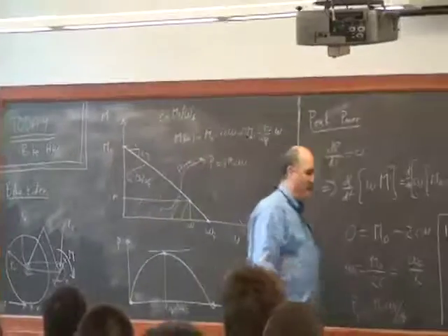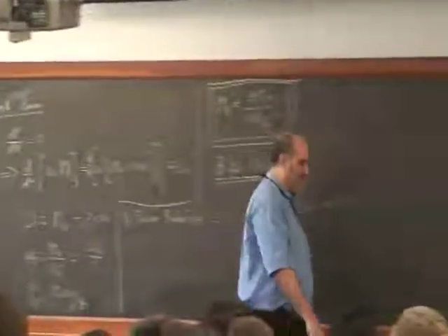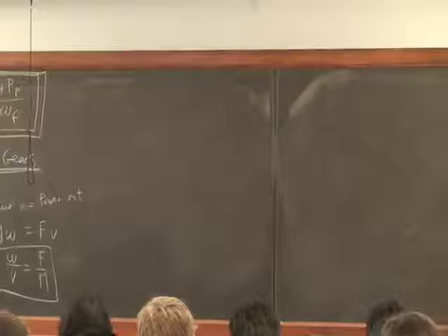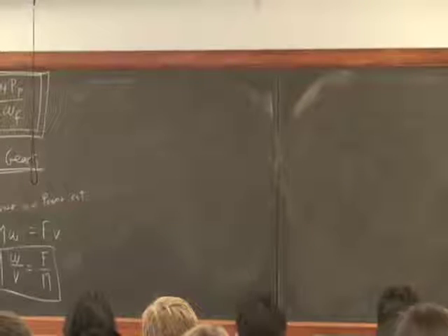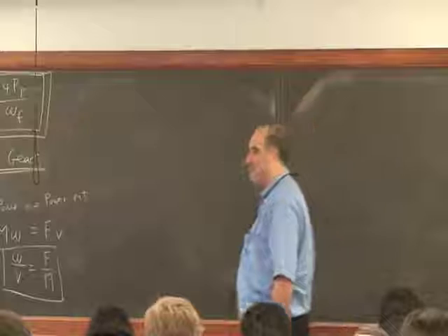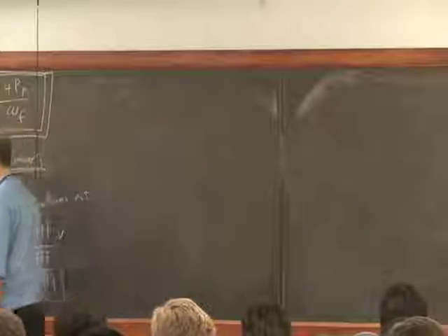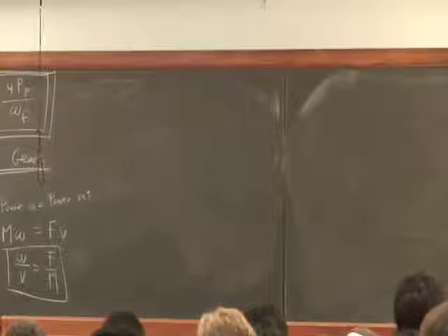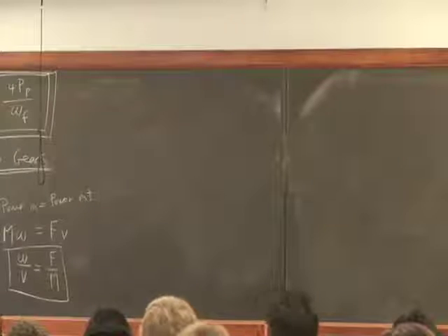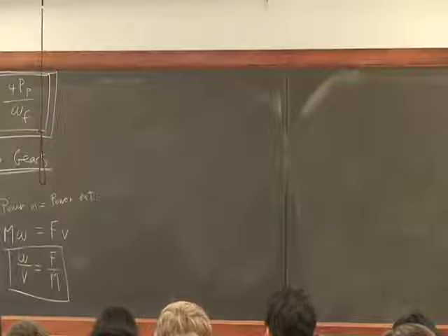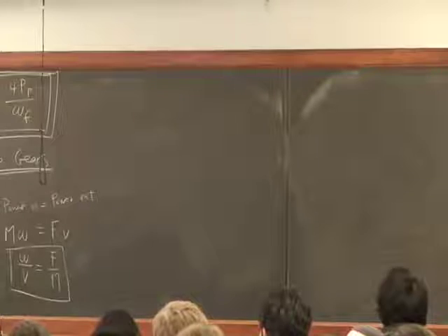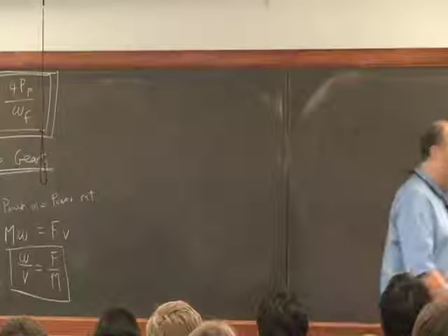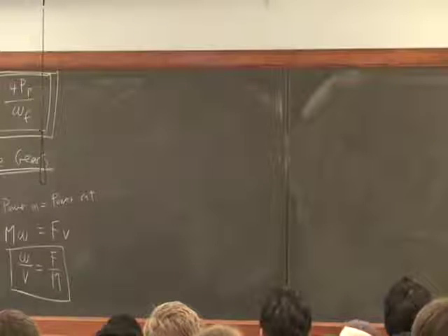And if you want to think about it in terms of a lever, the force which is closer to the axis of the lever has smaller velocity. The force which is farther from the axis of the lever has a bigger velocity. But the ratio of the forces, if the lever is going to be balanced, is the reciprocal of that. So the bigger force is closer, the smaller force is farther when the lever is balanced. And all transmissions work like levers do. So if you just think about a teeter-totter, it will tell you how all transmissions work.